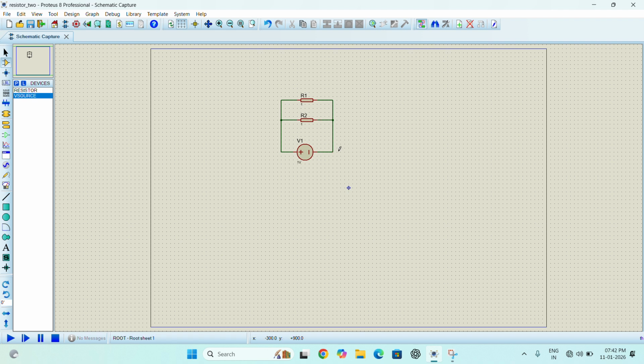You might be seeing that whatever the voltage difference between these two nodes is going to be 1 volt, because we can already see that in parallel we have connected it. Whatever this wire and this wire difference is going to be the same to this wire and this node, and this node and this node. So one thing you can observe from the circuit itself is that in a parallel connection the voltage is going to be the same across R1 and R2.